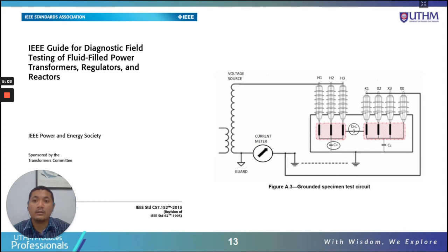diagnostic field testing or in-service testing of fluid-filled power transformers, regulators and reactors. Take note of the term here, fluid-filled power transformers. For dry type transformers, you have to use a different standard. This is specifically for diagnostic field testing, to test the transformer at site, for transformers filled with oil, fluid-filled.